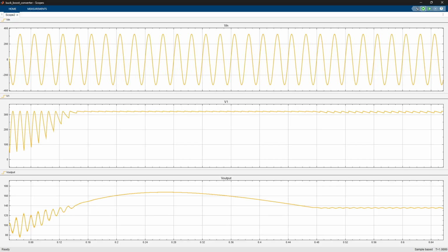And third, as I said, there is no feedback control. So the buck converter does not know the highest voltage it has, so it will just keep on increasing. And this overshoot is expected in the open loop drive.